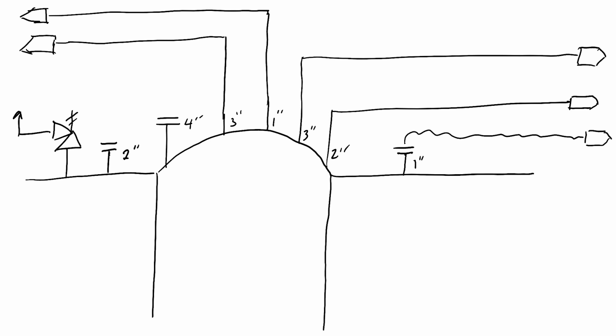Here we have a good example of how to depict a tank on a P&ID, one that has a bunch of nozzles, so it's kind of hard to get them all on the rounded top in the sketch. So we extended the top of the tank. That's what that line's depicting. Really, all these nozzles are on top of the tank. So a couple things to point out here. This really helps with spacing, really helps you to understand and see all the nozzles and see what they're doing. Another point is that we arranged these based on how we wanted the tags to go. And it's a more simplistic design.